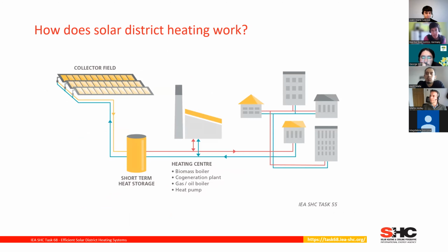This depends very much. There was a question in the chat on the renovation of your district heating plant already. I mean, you might have ones which are run at 120 degrees, you might have ones which are already run at 70 degrees. And the lower the temperature is, the better it is for renewables and waste heat to be integrated.